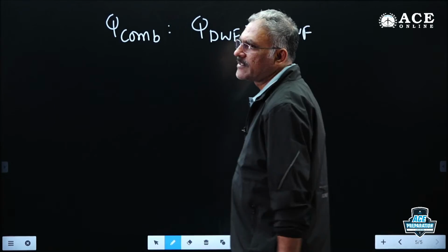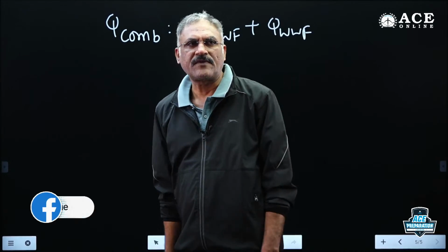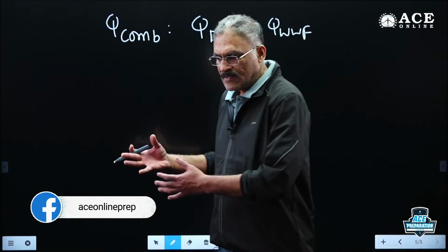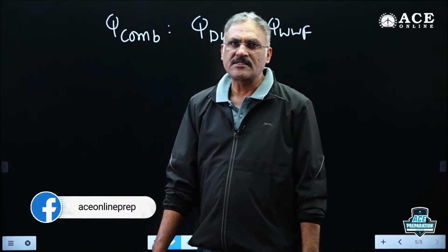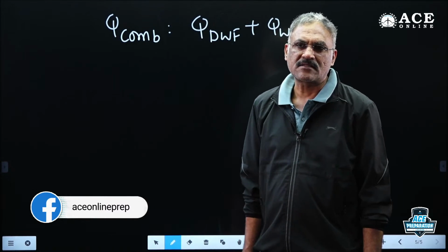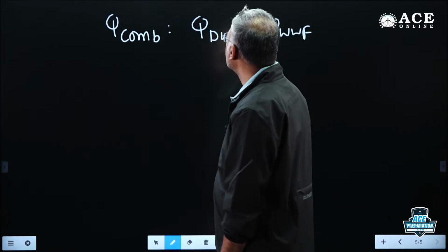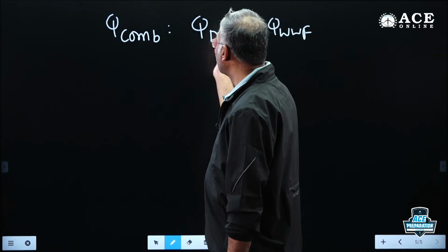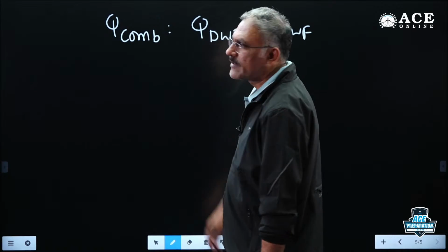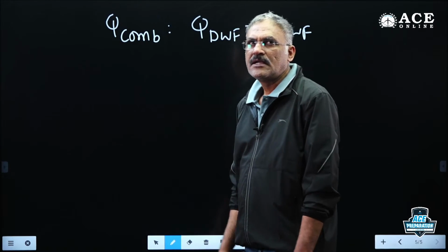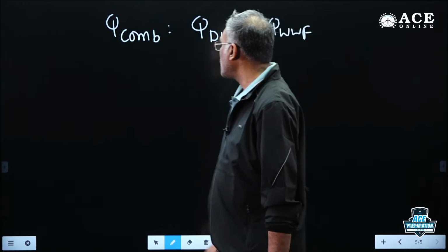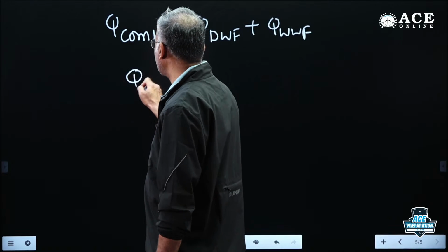If it is a separate system, the drain carrying dry weather flow is designed for dry weather flow. The drain carrying storm water is designed for storm water. Separately we work them out. A combined system has to carry both dry weather flow and wet weather flow taken together. Design of sewer means finding the diameter of the sewer.